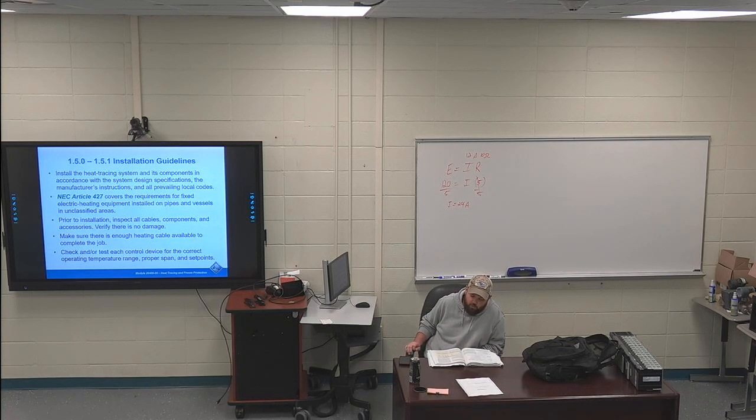So part 1 of the question is from the first couple sentences of that second bullet point on page 15. To verify that the heat cable has not been damaged during shipping, test it for continuity and electrical insulation resistance. Test the insulation resistance between the cable and conductors and the metallic grounding braid in accordance with the cable's manufacturing instructions. Flip it over to page 17.